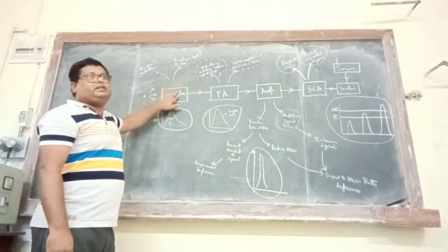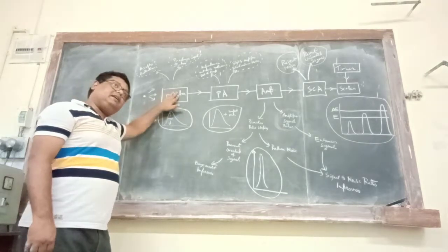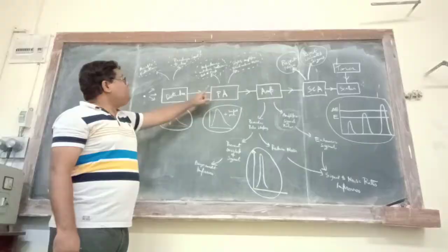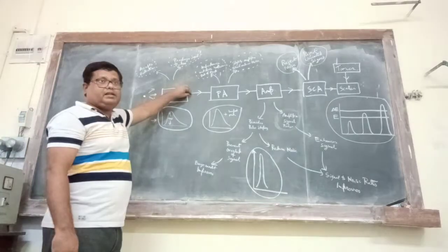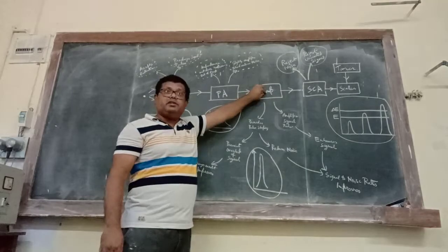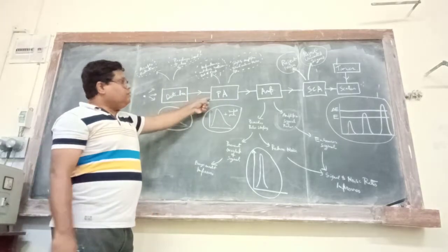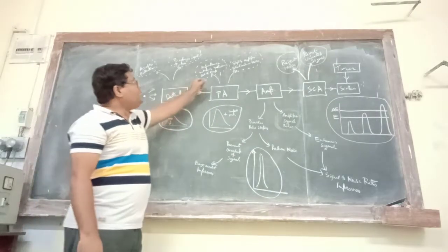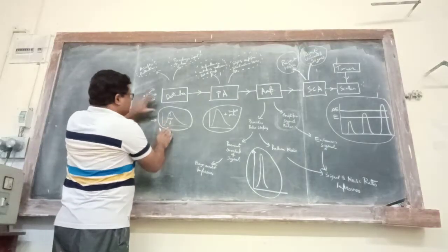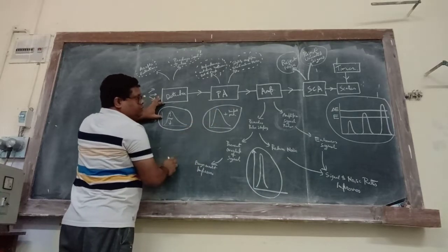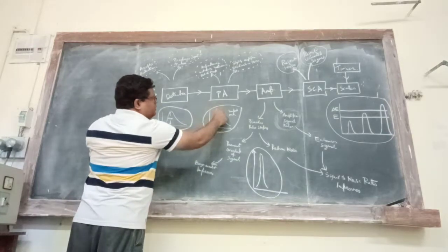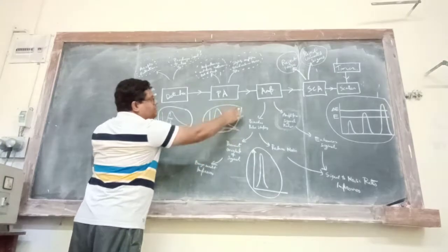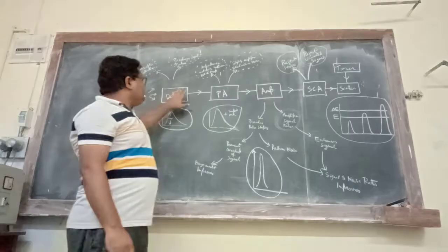So the next component after the detector is not the amplification part, but rather an impedance matching device, which is the preamplifier. What does it do? It basically matches the impedance between the output of the detector and the next very important component where the main amplification is done, that is the amplifier. So it is an impedance matching device. Along with this, the preamplifier also slightly amplifies the pulse and reduces noise. Here you can see the detector pulse, and here the y-axis is a little bit more. So this is the preamplifier. Again you see it is similar; nothing is happening to the tail part of the pulse, and this has already matched the impedance between the detector and the amplifier.